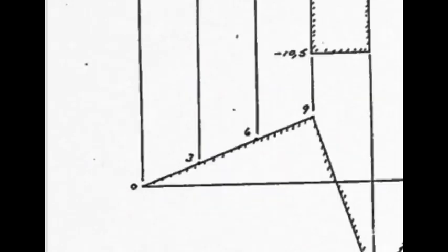Well, as we said before, you simply place your hand and expose one or the other side of the beam. In this case, I'll expose the left-hand side because it's the easier side. So my hand is here, and it is obscuring all of this, and it is exposing this piece here. What is the bending moment? Well, we've got 1.5 times 2, which would be 3 kilonewton meters. So we start by drawing our bending moment diagram with a 3 value at this point.